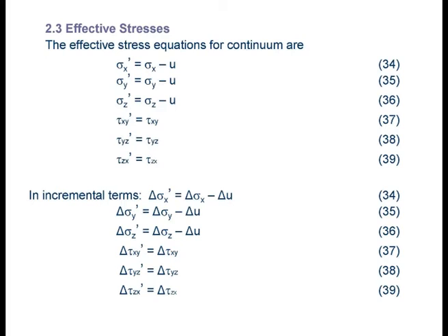And you'll note that as we move into elastoplasticity and strain hardening elastoplasticity, we'll be going more and more into this incremental approach. The reason you go into the incremental approach is because, as people always tell you, soil is inherently non-linear. That's why you use Mohr-Coulomb. Soil is inherently elastoplastic.